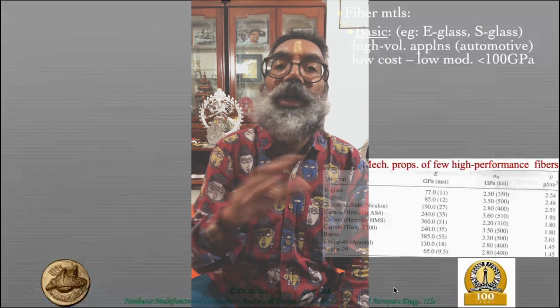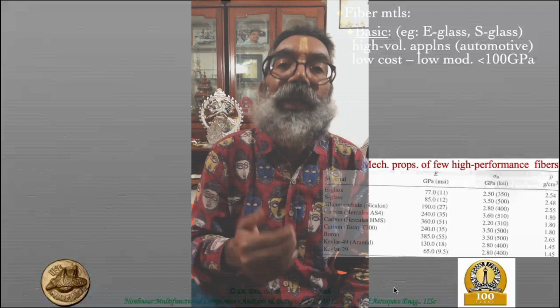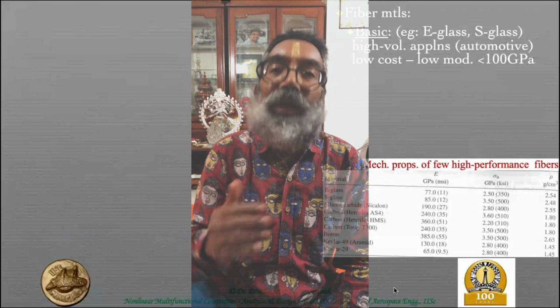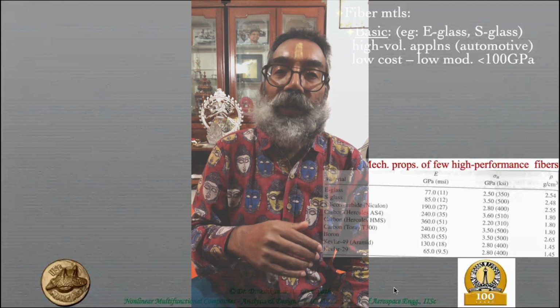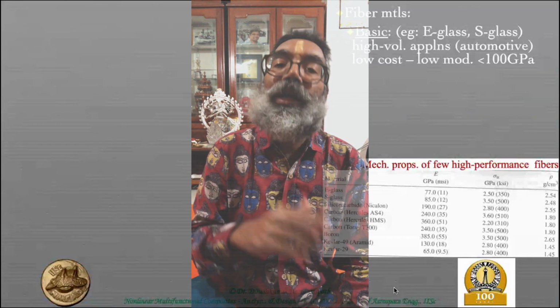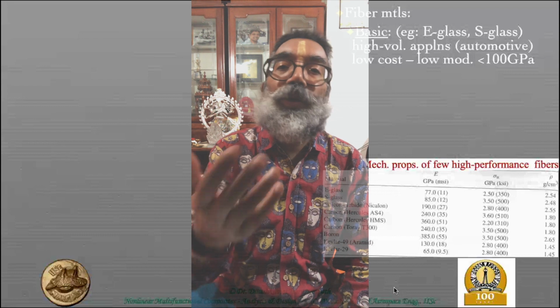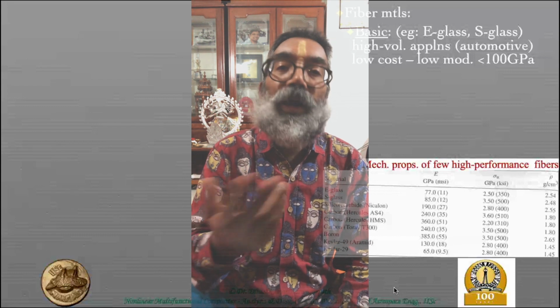There is going to be a difference. And so certain directions can be designed for lesser strength and stiffness, and it's still okay compared to certain other directions, because you know that loads will come in those directions as well, but they will not be as high as the loads coming in the primary loading direction, which is what you're designing most of the fibers to be along.